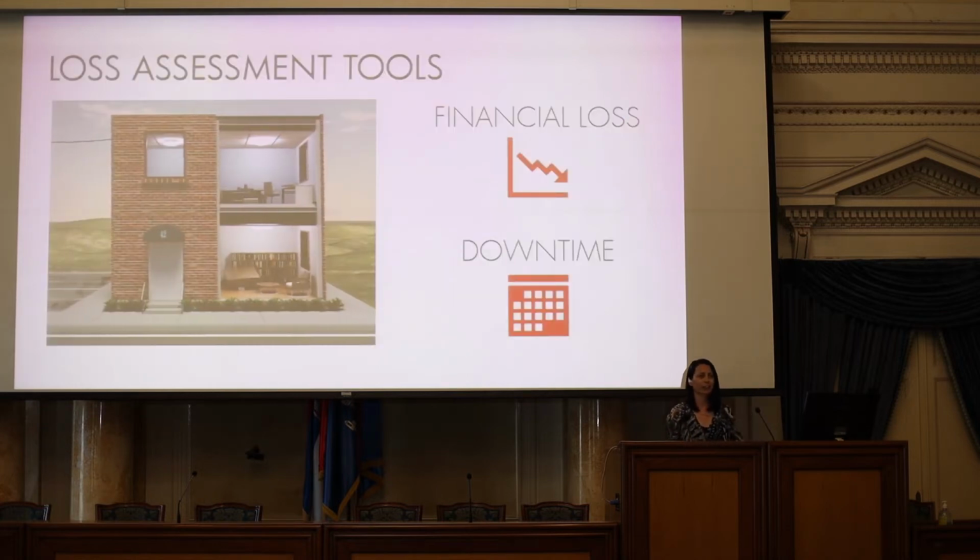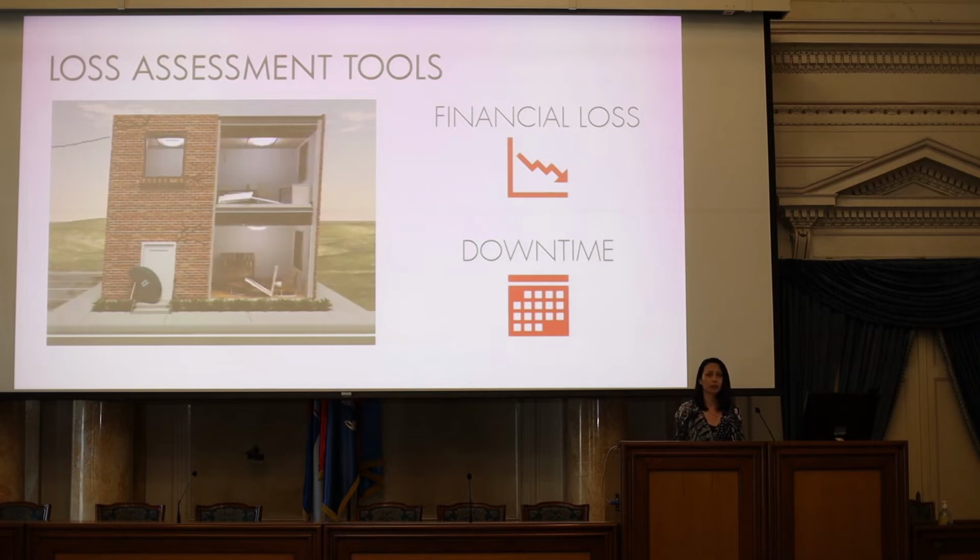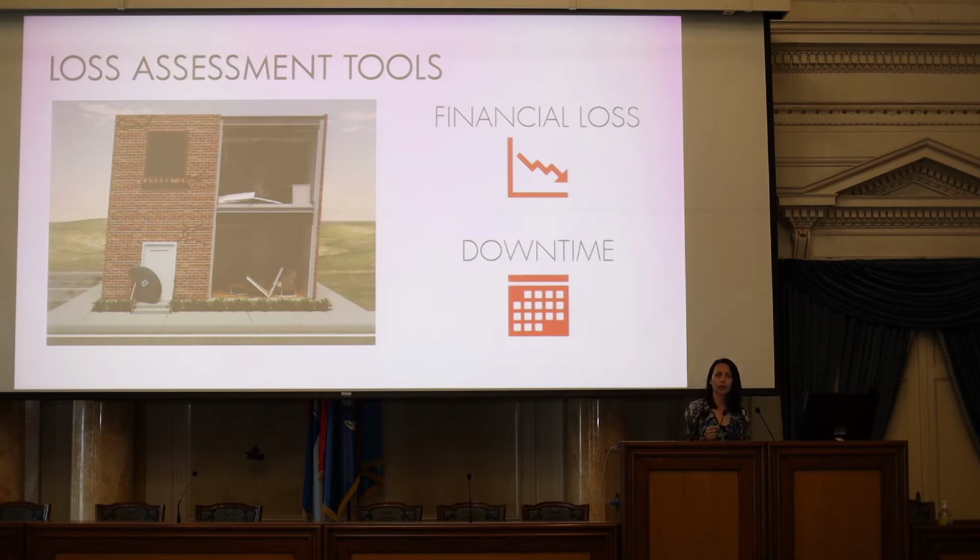And if you're wondering how we can do this, FEMA, the Federal Emergency Management Agency in the United States, has invested a significant amount of resources and provided it to engineers to create the tools for loss assessment analysis. And their greatest contribution lies in the development of the fragility library, where, for all structural and non-structural components, they're mapping structural response into damage for each building component.